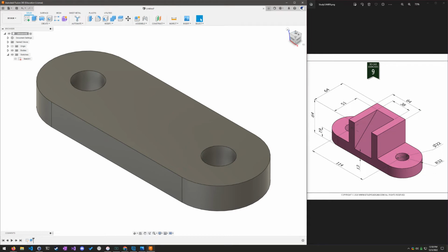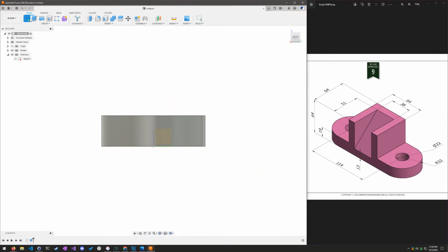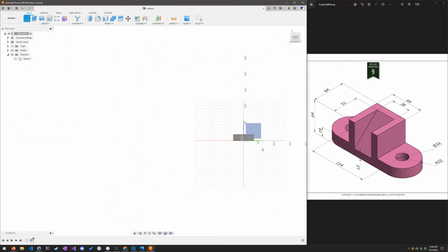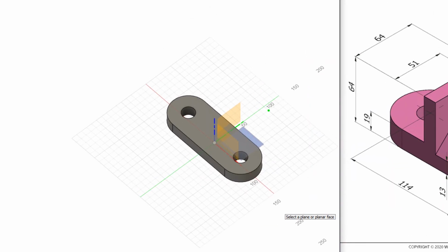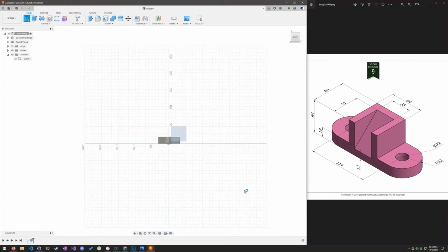So now I'm going to click right on the view cube to create my next sketch inside the ZY plane. So I want to draw where this piece is getting cut in half like that. That's where I want this next part to start. So right on the view cube, clicking on this square. Don't click on the piece, click on the square.